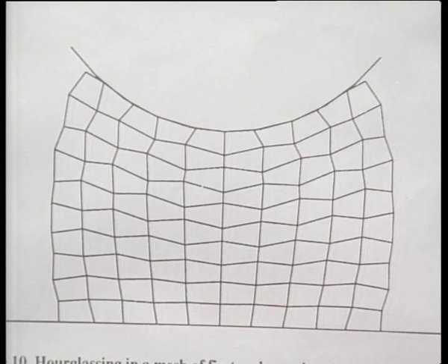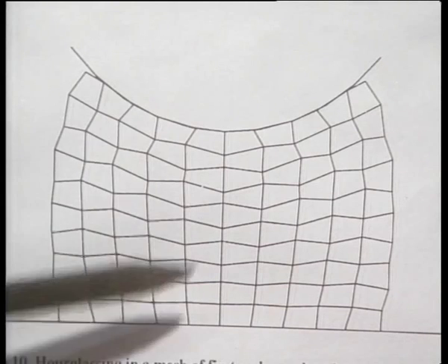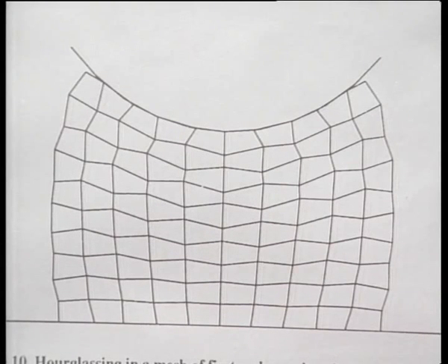I will explain Hourglassing in a minute, but I want you to look at the result and recognize Hourglassing. In fact, many students have come and told me, sir, I am getting a result like this, some jagged things. What is happening? So first of all I want you to recognize that if you get a jagged front like this, your mesh is undergoing what is called Hourglassing. I will explain that in a minute.